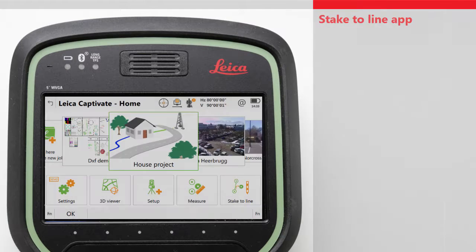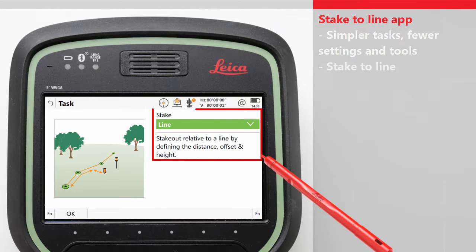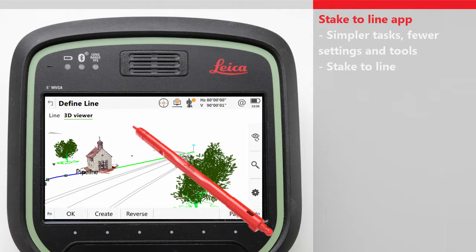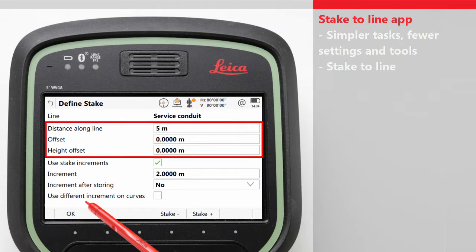The stake to line app allows a number of relatively simple tasks to be performed. I will only describe a few of the tasks and the basics here. Other videos will give more detail. Firstly, we need to choose the task. The stake to line task allows the line to be selected, the distance along the line, the offset from the line, and the height offset of the location to be staked.